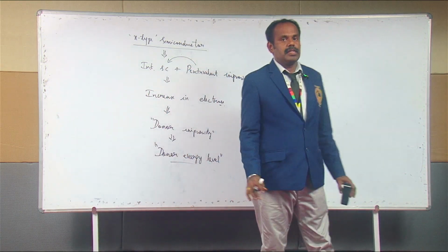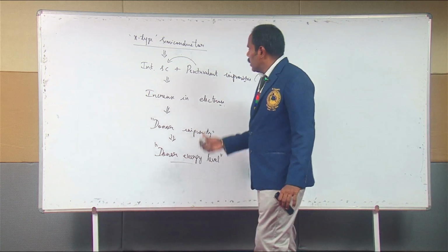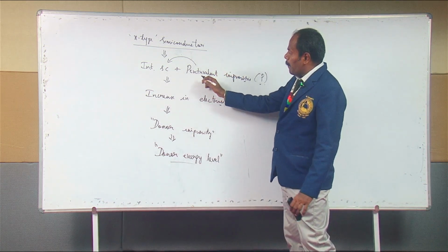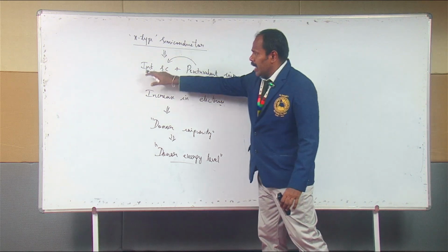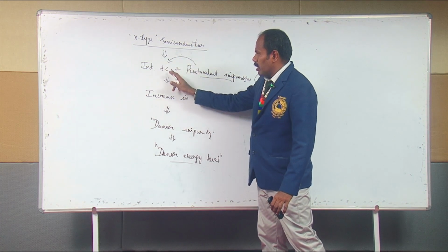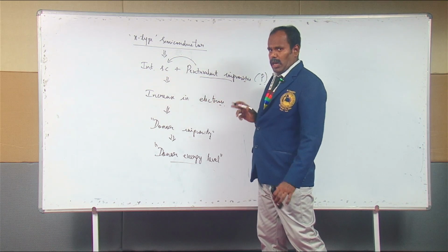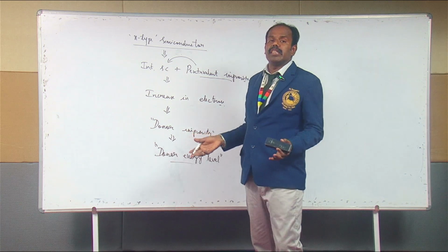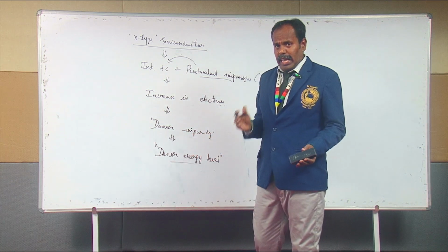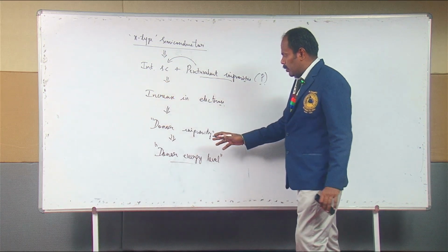Okay. So these are the basic points that we must know related to the N-type semiconductor, where we will be doping the pentavalent impurity atom into the intrinsic semiconductor, and this addition is going to lead to an increase in the free electron concentration. Obviously, when you have an increase in the free electron concentration, that will be reflected in an increase in the electrical conductivity value.